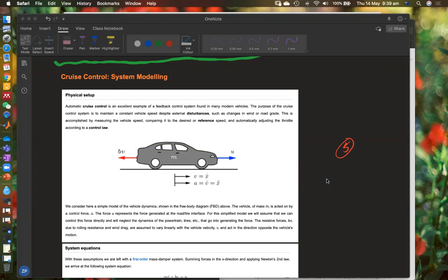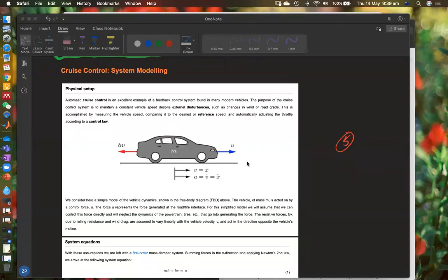So for the project, the first step is to identify an object, what kind of control task you want to do. And then you build up a mathematical model for that. The mathematical model we are talking about is mostly differential equations. It's the relationship between the input and output, normally a differential relationship. It's not direct, input straight to output, because we're talking about a dynamic system. A dynamic system has a certain way of storing energy, so the input doesn't go to the output directly. Normally it takes a bit of a delay for the input to be reflected in the output. And that's our mathematical relationship.